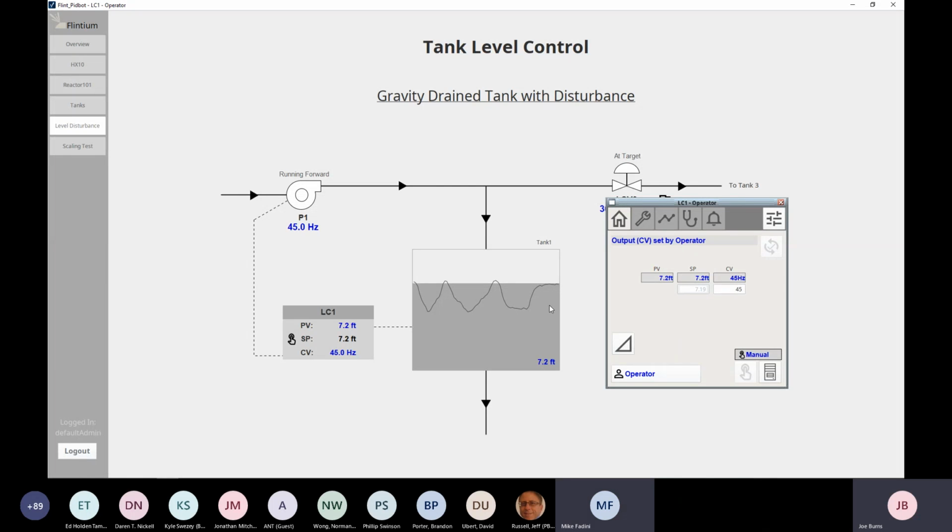Okay, and I wanted to get back. I have another question on deadband. Sure. The question is, isn't deadband bad as reflected in the formulas? So that is dead time, which is a little bit different. That's how much reaction delay there is in your process to a change in CV. One classic example of that is a transport delay.